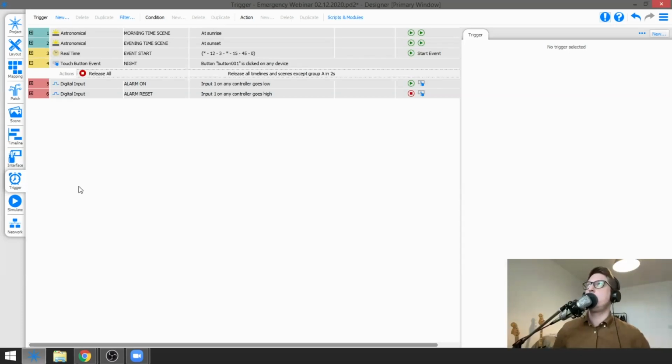So we do have a Rio device that is capable of controlling outputs, but I believe its maximum voltage is 48 volts. Is that correct? Yes. So obviously, you could have a Rio control the power going to a fixture, but the 48 volt limitation is there, and you can't really use more than 48 volts because you'll blow the output.